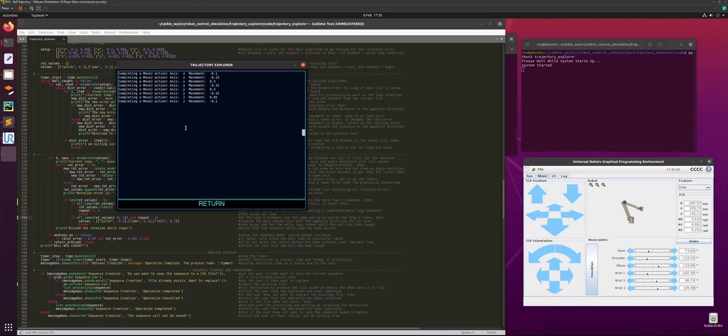The reason for the MoveJ type of movement is because the inverse kinematics function that the UR10 uses takes into consideration the dimensions of the robot and the position of the robot. Therefore, when you send it a position that it needs to reach, it considers all of these factors so that the robot does not go through itself.